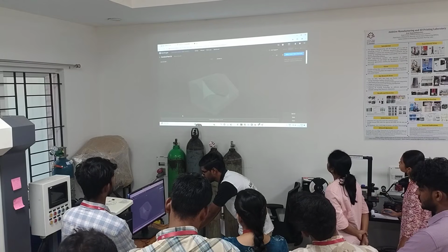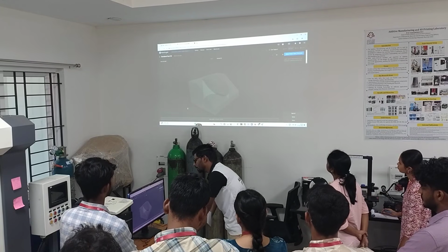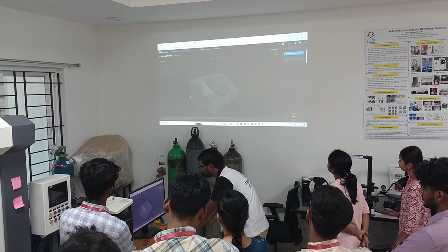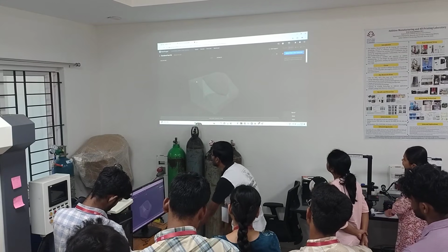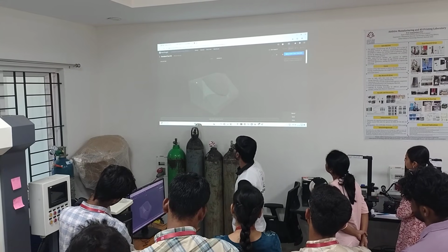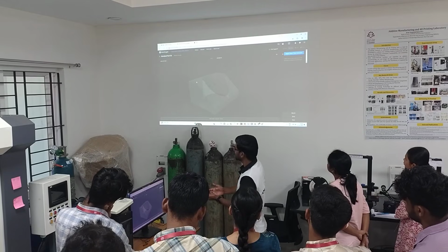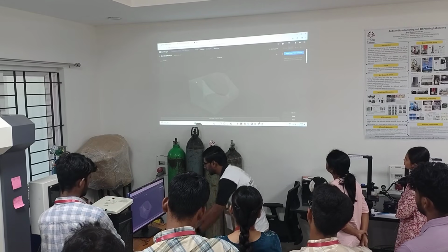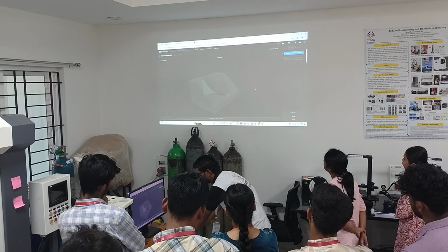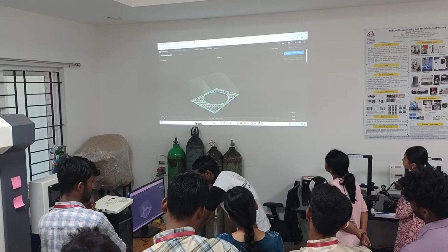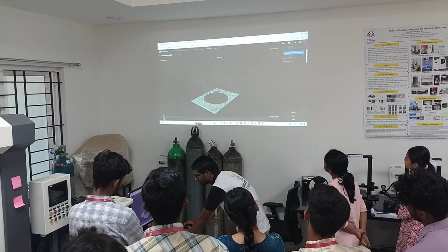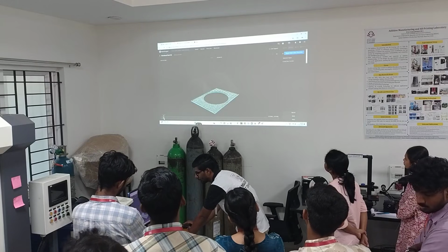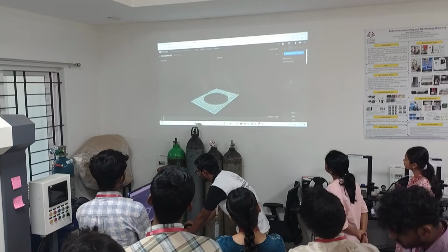There are some restrictions. From the side wall, from the bottom, as well as from the top, there must be a gap of at least 2 layers of the plastic or the matrix. Only after that can we place the fiber material. So let me start from the fourth to fifth layer. We have 2 layers of carbon fiber that I'm going to add.